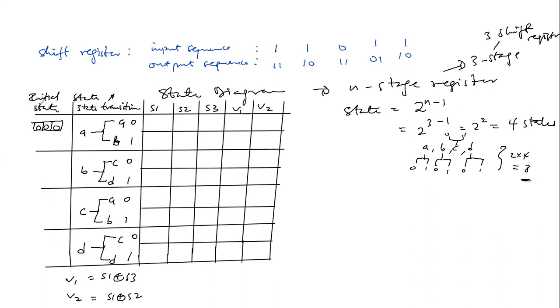So once we take this, if the initial state is all zeros, and then we plug in a 0, it means that this 0 will take on the first bit, then these other zeros will be shifted, and the last one drops. What if it's a 1? So it means that this first portion will take on a 1, then the next 0 shifts, and then this 0 shifts, then the last 0 drops. So if 1, 0, 0, let's draw this.